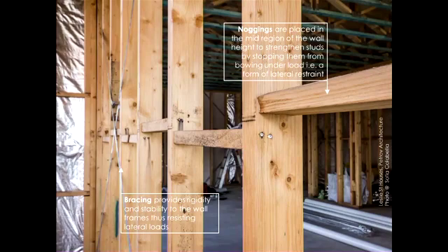But there is also another thing that you need to notice. They are not aligned. So why aren't they aligned? Because you wouldn't be able to drive the screw or the nail to place them. So that's the reason why they're not aligned. It's not really important that they are aligned for structural purposes. They only need to reduce the height of the studs. So that doesn't really matter. But you need to be able to place them easily. So that's why you've got that shape.